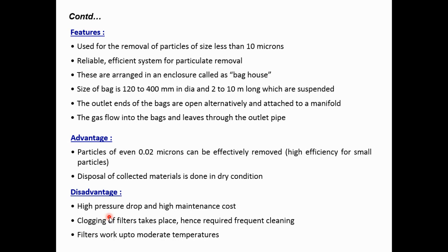If one layer of dust attaches outside the fabric, then even if you are applying the mechanical sucker or the jet of air, sometimes it cannot be cleaned 100%, so clogging of the pores inside the bag can take place. Due to that, the air pressure drops severely, and the chances of the bursting of the bags are very high. If the bags burst, then the maintenance cost is high, because there are a large number of bags inside the bag filter.